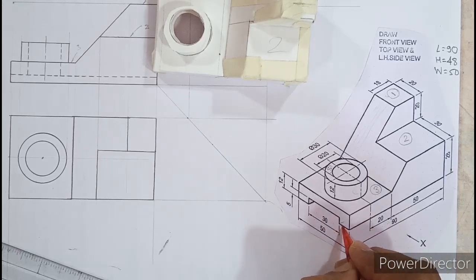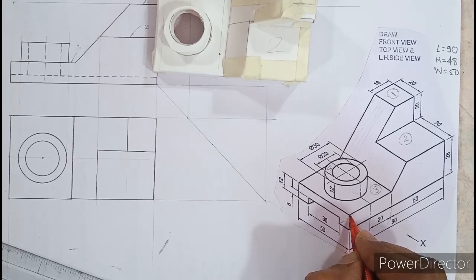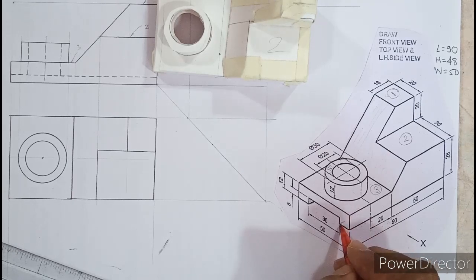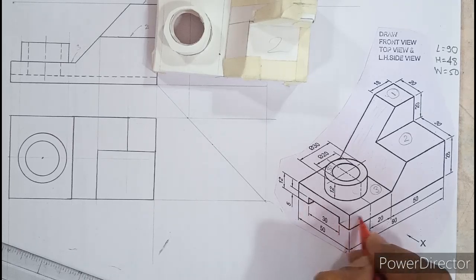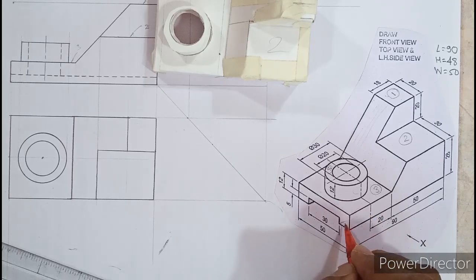Whenever you find two lines intersect, it is obvious that a third line has to pass from that corner. Each and every object is made up of a corner, and a corner should have three edges: length, width and height. Similarly, if you look at this corner, you will find two edges. One is moving up along the height, second is along the width. So obviously the third one has to be along the length, which is not seen. So in the top view you cannot see both the edges.